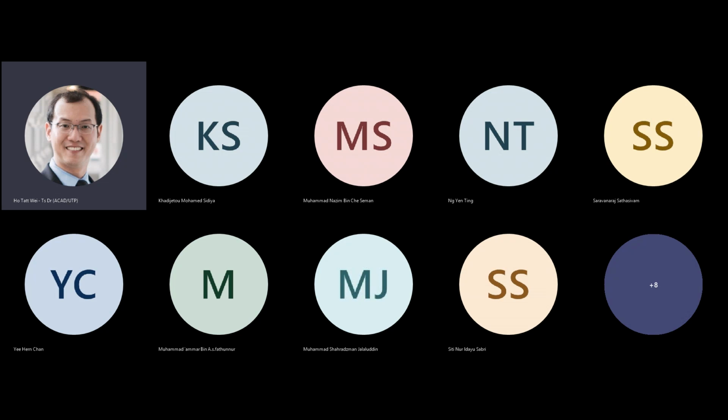We start by first defining the truth table, and I would like to encourage you to always start with the truth table, at least at the beginning. And the multiplexer is one of the examples of what we call a complete digital logic family. So I'll give you an example of one complete digital logic family. If you have a NOT gate, an AND gate, and an OR gate, you only need these three sets of gates to build any combination of logic circuits. Only this set of gates forms a complete logic family.